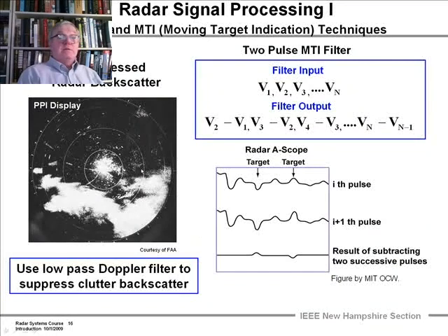Now that we've got the data coming in, we can display it in an analog fashion, as if we were looking down on a display of what the radar saw. It transmitted out in this direction, and these white places are the areas that were above threshold. In this case, the radar had a target right out here, and this was a long exposure photograph.